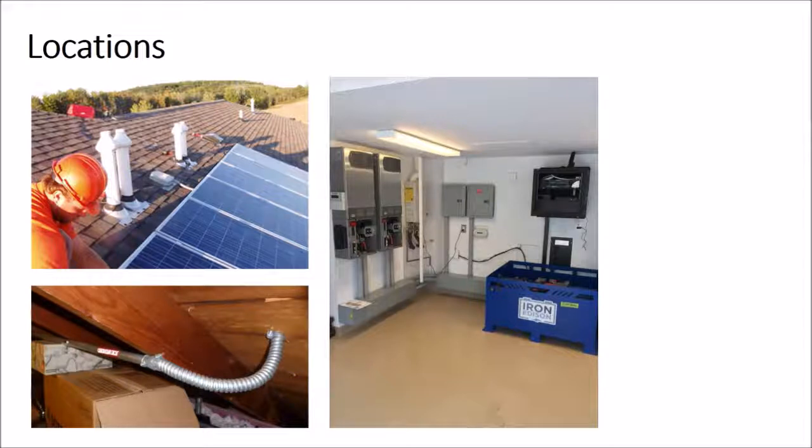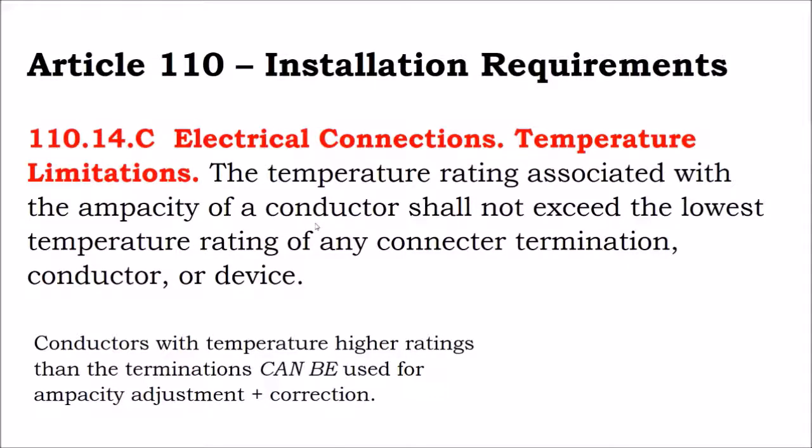So you don't need to worry so much about your material selection and what wire type you're using if you start with the premise of, okay, is my environment wet, damp, or dry? Is it going to experience high temperatures, or is it air conditioned and inside? Are there any batteries in the room, so I have to worry about a corrosive environment? Or am I right on the coastline, or am I on a chicken farm? What's a corrosive environment versus if there's no gas in the area? And from that point, that's what drives your material selection.